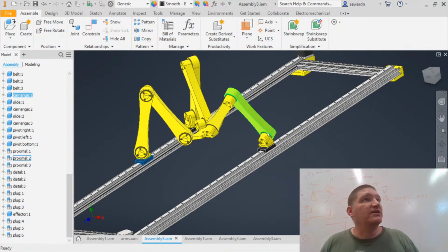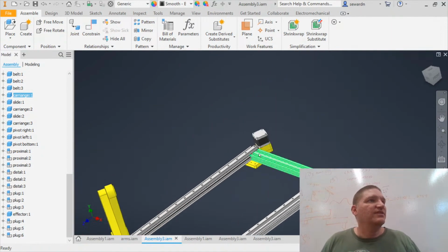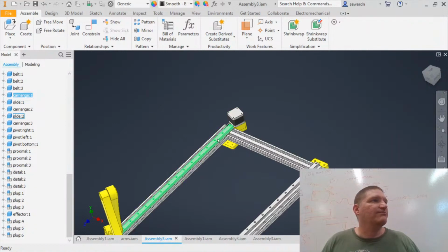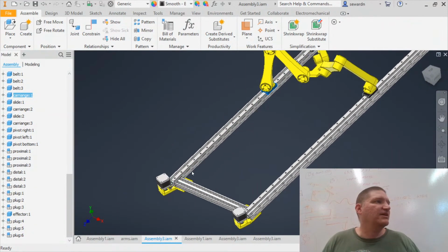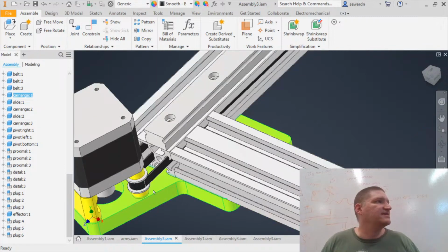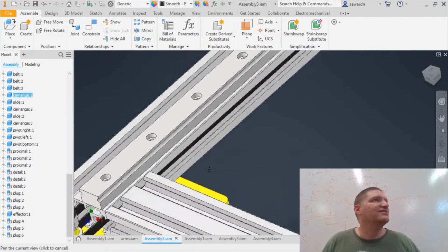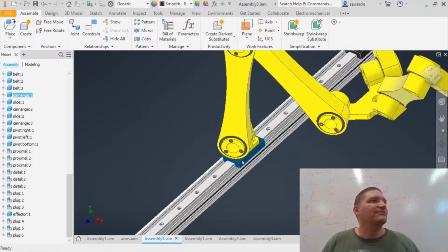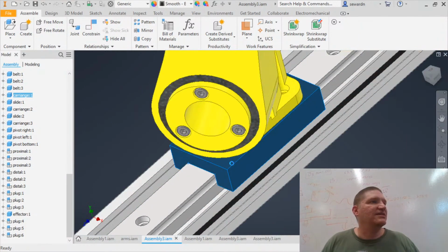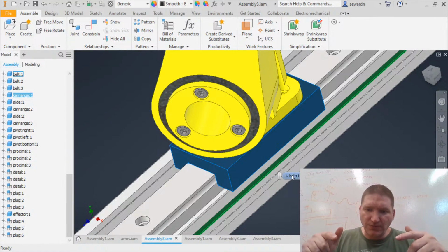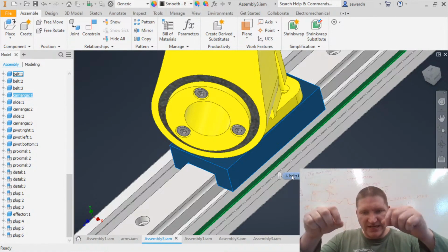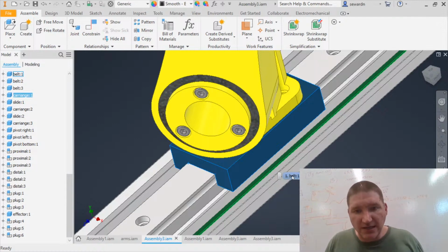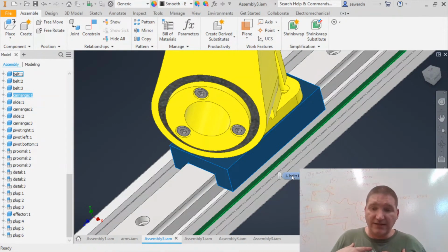Well, as drawn here, there are steppers that drive belts that go through the rail. So there's one on each side. You can actually see here that the belts go through the extrusion. I don't have it shown here, but I'd put a little piece of plastic underneath this, and it would reach down and grab onto the belt. The belt would not be a continuous loop. It would have ends, and you could bring it out and use that for tensioning, yada, yada, yada. So that's how I'm planning on driving this.